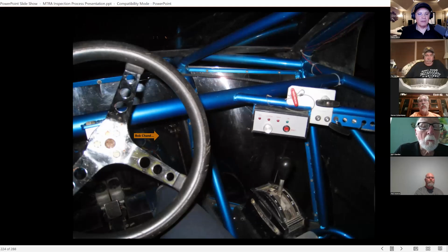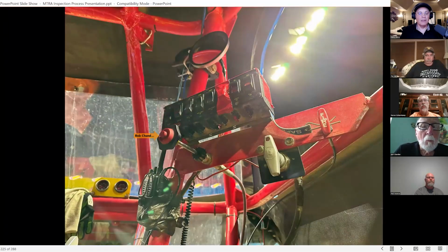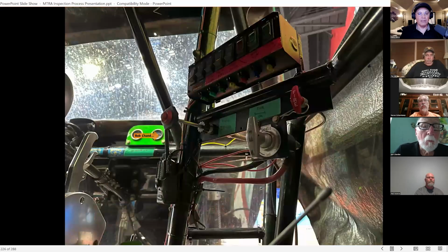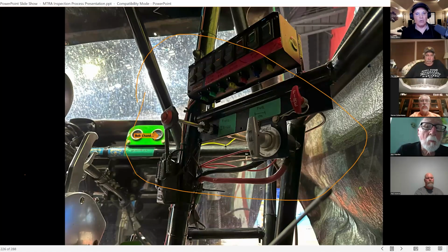It's very important that it be a push to kill. We have seen situations where trucks have a twist type in the cab. That won't work. The idea of the push kill is that in an emergency, if the throttle hangs or something, the driver needs to be able to quickly hit that button, not have to grab for something or turn something. In other words, it needs to be to where he can do it with his eyes closed. He can just smack that thing. It's one of those things you hope you never have to use in an emergency situation, but I think we've all experienced points at one time or another where we had to use it.